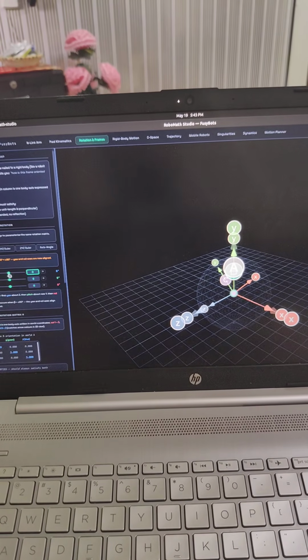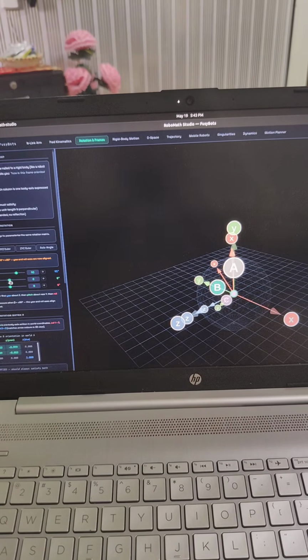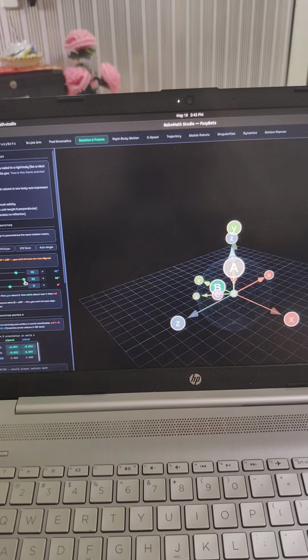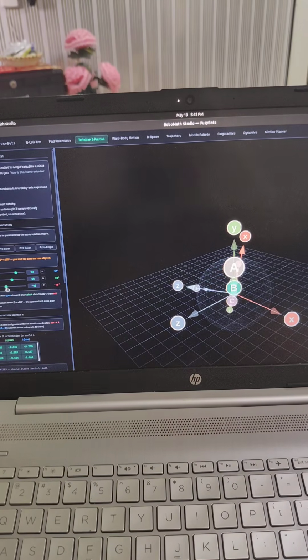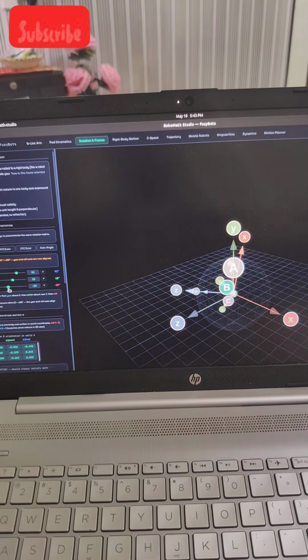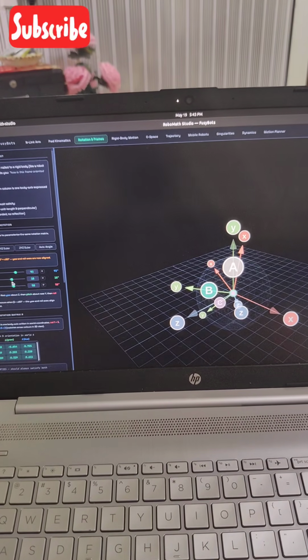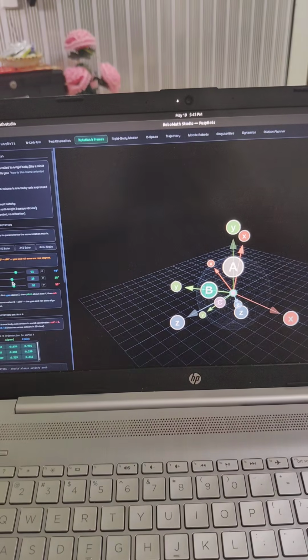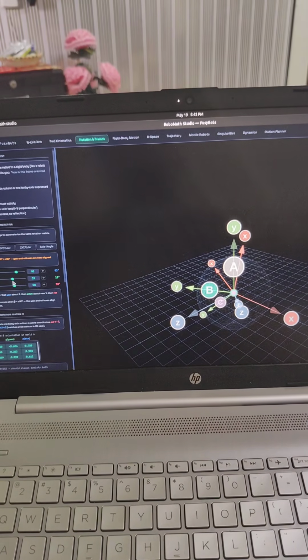See, if I rotate about z 90, right? So this is z 90. Now I rotate about y. This is the rotation about y, right? And now this is the rotation about x. See, we can differentiate between the rotation of x and y. That means if there is no lock, we can easily differentiate between these two rotations. Therefore, it is not pointing to a gimbal lock. So gimbal lock in ZYX Euler angles only happens when beta is plus minus 90.